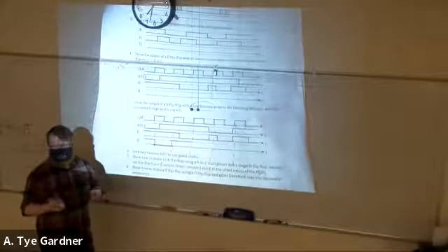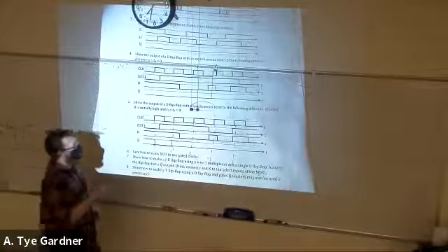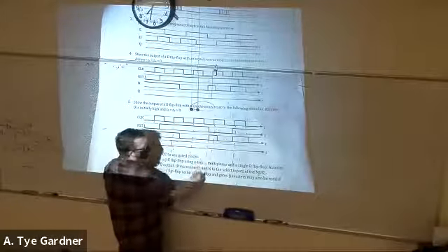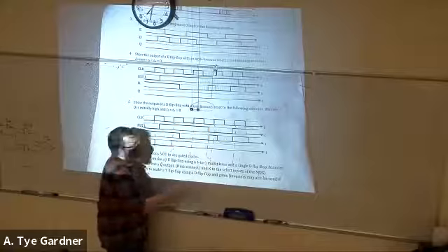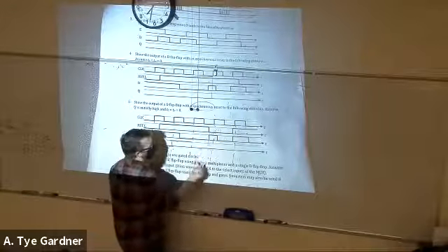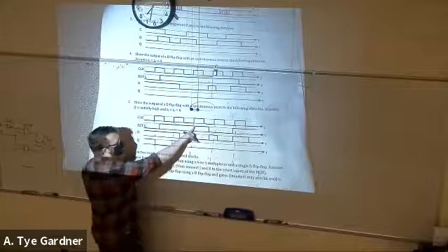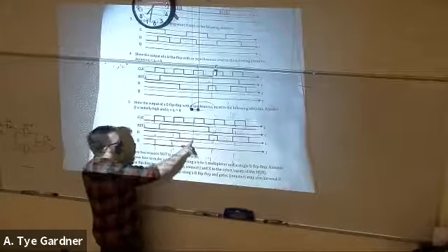Identify where it could possibly change. If this was an asynchronous reset, then I would go out and add this one, because it could change there. But it's a synchronous reset, so it doesn't matter. All right, clock edge, not resetting, data is 0.